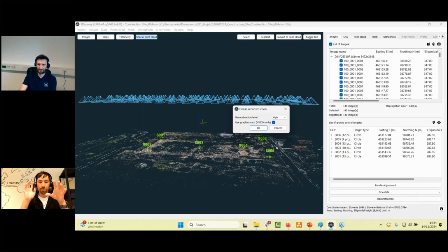This is kind of the best time performance. So 3D survey really calculates a nice point cloud out of it. With the high level, you get great results in most cases. What is important, it's great to have an NVIDIA graphics card, then this is checked on and this works nicely. With the high preset and with standard graphics cards like a 4070, you can handle 100 images per hour. If you have 2 or 3 graphics cards, you can go from 200 to 300 images per hour on a high level. You can go even harder to extreme, where the time is double the time of high and so on, or with a medium or lower level, which is 4 times faster at the end.